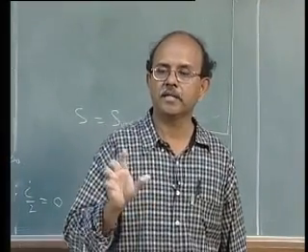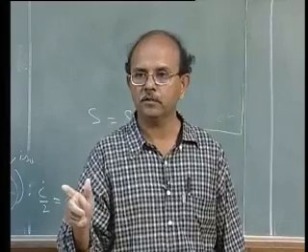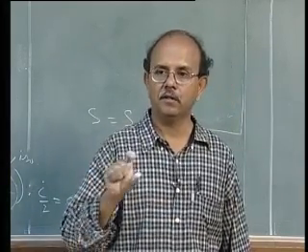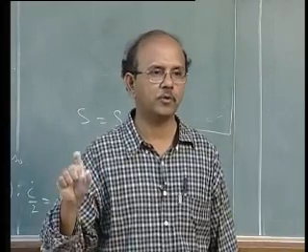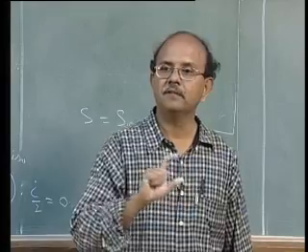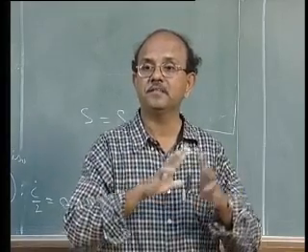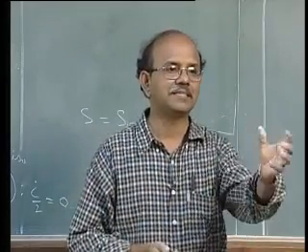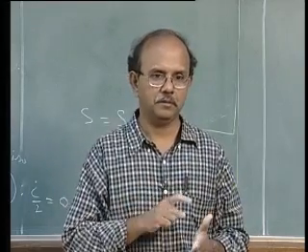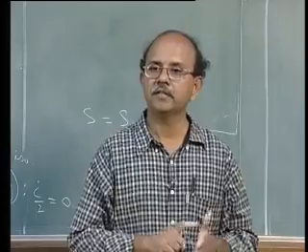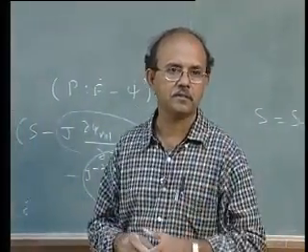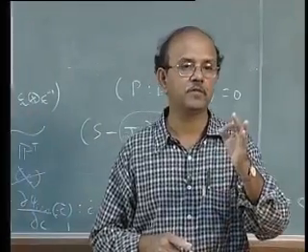Concept number 3, what did we say? We said that materials can be isotropic or anisotropic. We went to isotropic. We said that the psi can be written in terms of I1, I2 and I3. Concept number 3. Then 4, we expressed in a more general form S, P and sigma. The next concept is that we said it can also be expressed in terms of stretch, and we expressed sigma, S and so on in terms of stretch.